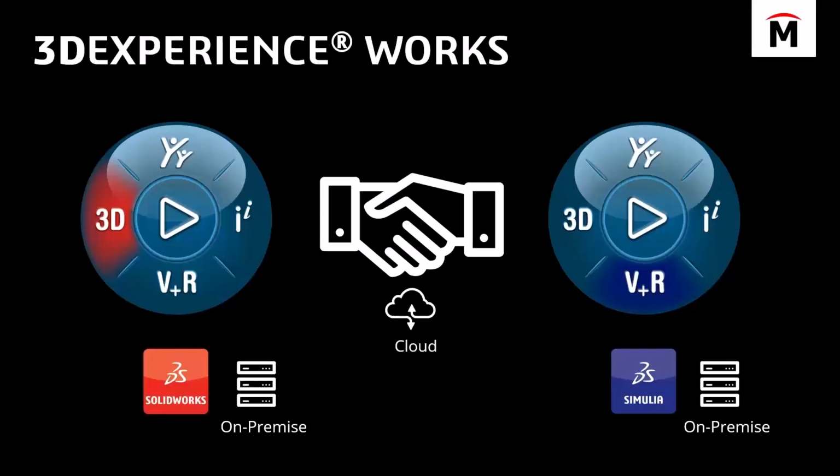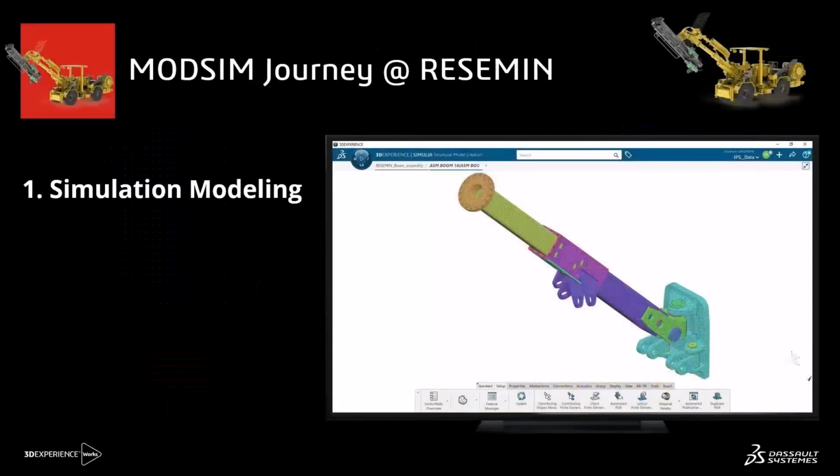Let's get into now the heavier program under the Simulia brand, this one being that structural mechanics and durability for fatigue. Now, this FEA has a 3-step process, maybe slightly different from what you're used to in SOLIDWORKS. So first, we're going to build a finite element model, or FEMREP. That's going to include our materials, our meshes, and our connections. And of course, it's all linked to the actual SOLIDWORKS geometry.